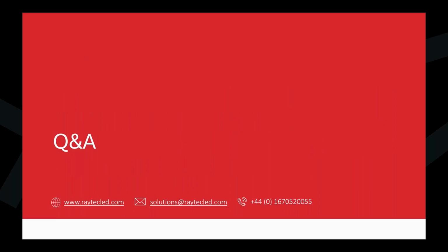That's actually less important if you're looking at other plates. For example, we've been working on big applications in the Middle East across Saudi and UAE, where they found that that's not actually a necessity, primarily because the plates are transmitting diffuse reflection, and so they get just as good performance if the camera and the lighting are slightly separated versus on the same axis. So in answer to that question, yes, if you're looking at European or British plates or other nations with retro plates, but not necessarily the case if you're looking at plates with a more diffuse reflection characteristic.